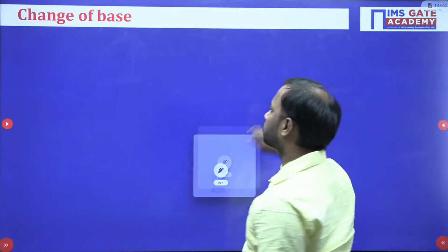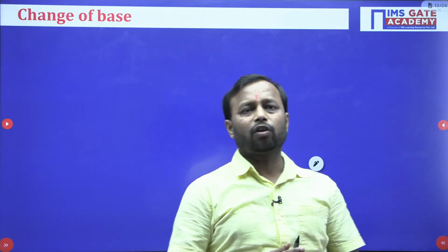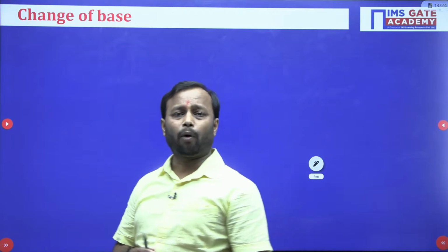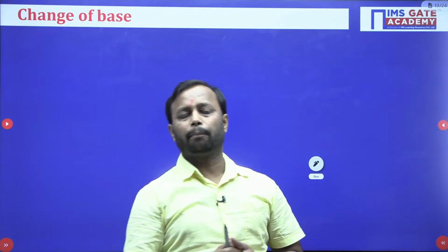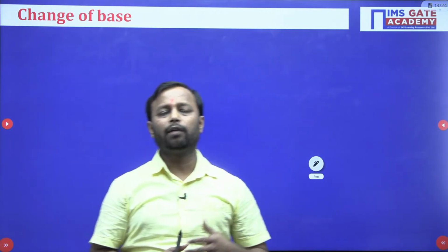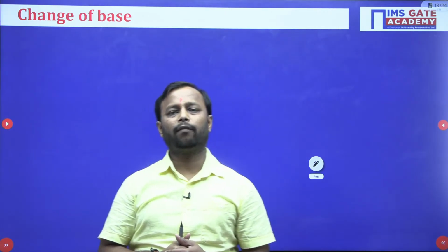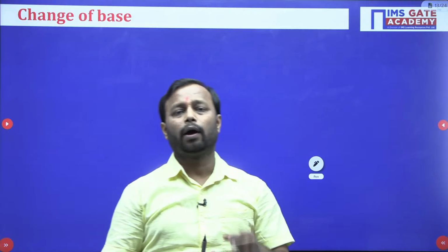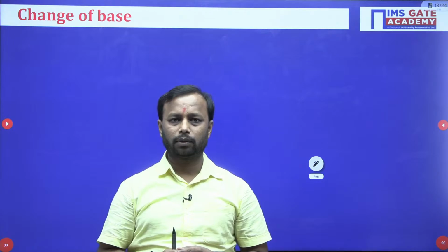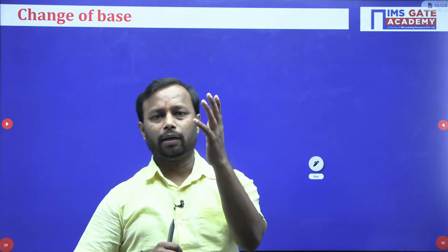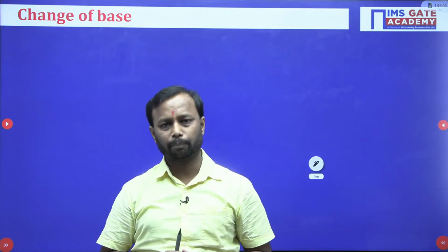Come on, now let us come to one more topic, that is change of base. Now this change of base, why is it important? See, as I told you, we need to choose the base value as per our convenience, but it is not always true. We will have to consider the base value as a rated value when it comes to the practical scenario. Okay? As I said, in a transformer the rating that is mentioned is your rated rating, so that will be chosen as a base.